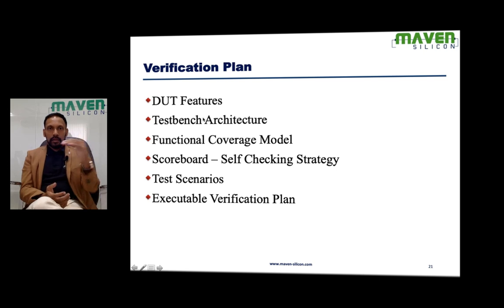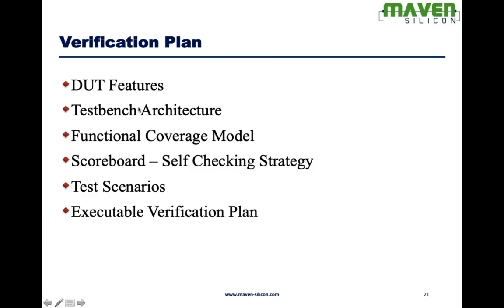And the coverage model. It will have all the details of cover points and cover groups. So in SystemVerilog, basically we have the concept of functional coverage. So during simulation, we generate functional coverage, and we try to map the functional coverage with the DUT features. That's how we are going to track the simulation progress. So there may be questions like how much we have done in terms of simulation, how much more time is needed.